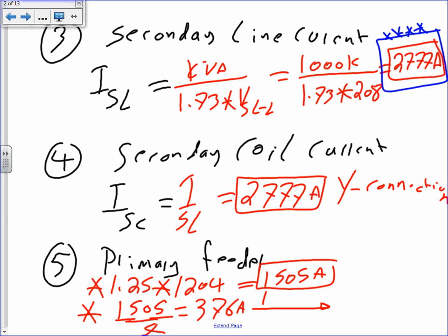Then you go to table 310.15(B)(16) under which column? The 75-degree column. And you will get the following. How many sets? 4 sets of what? Why am I stuck with the number 5 today?